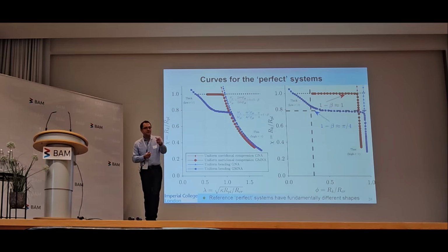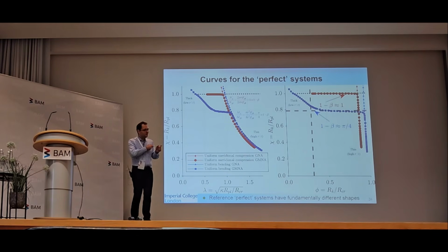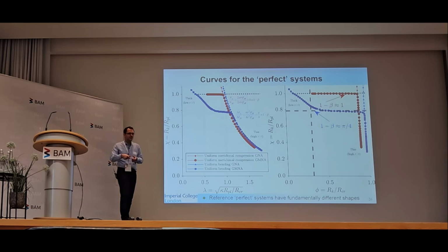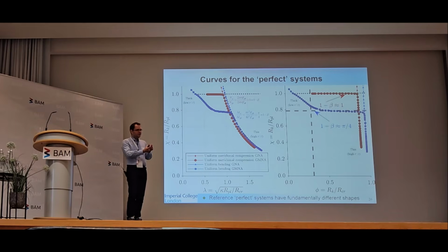you have a little bit of the circumference initially that is yielded. It's just a little bit. But remember, this is a thin shell, and this is still buckling under bending, so locally you have conditions that are similar to uniform axial compression, which means that you get a buckle that is an axial compression buckle, which is very small. So even though not much of the circumference is yielded, the buckle isn't very big either, and that little bit of the circumference actually happens to cover most of the buckle.